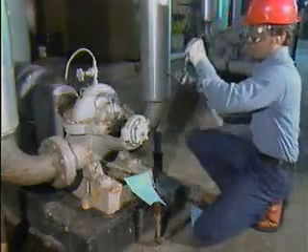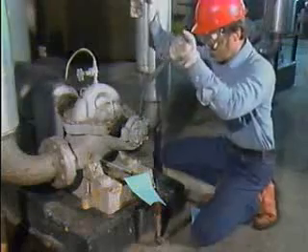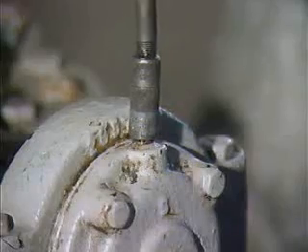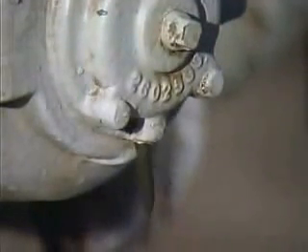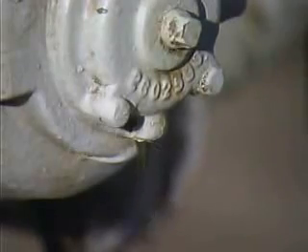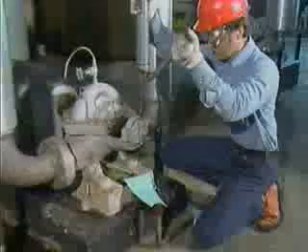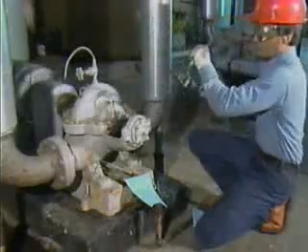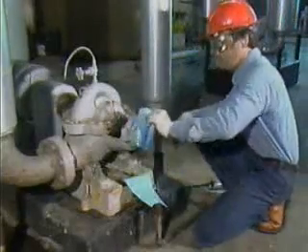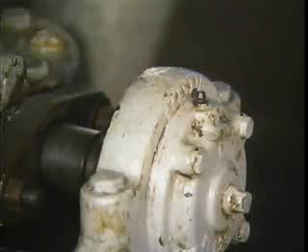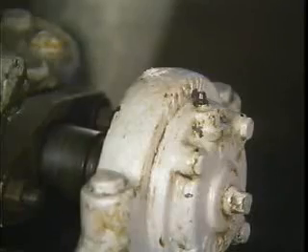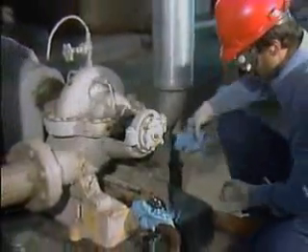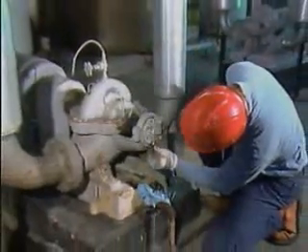Then connect the grease gun to the fitting and slowly add the specified amount of new grease while the machine is running. Don't over-grease the bearing. Typically, with a hand-operated grease gun, you should apply no more than 3 shots of grease at a time. Next, disconnect the grease gun from the fitting and wipe the fitting clean. Then, allow the machine to run for a few minutes with the drain plug still removed. As the machine operates, excess grease will be forced out of the drain hole. After a few minutes, wipe the drain plug clean and put it back in the drain hole.